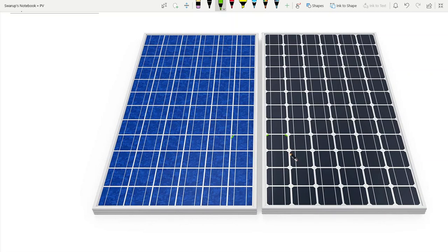So any idea why? No? Okay. When you talk about polycrystalline material, is there any preferred orientation? Nothing, right? The grains are oriented in any direction, randomly oriented. So when you make this kind of polycrystalline wafer or sheet, we don't need to cut in a preferred direction. You can cut in any direction because these grains are randomly oriented.